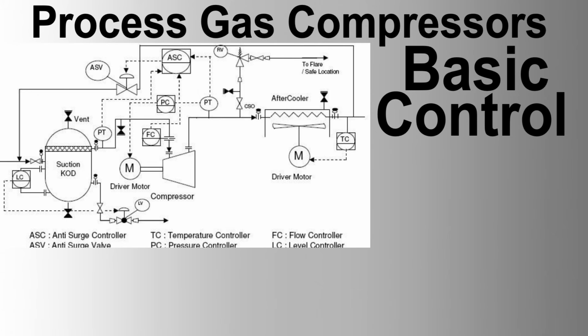Controller, anti-surge controller, processes flow and pressure signals to detect potential surge conditions. Recycle valve, RV, opens to recycle gas from the discharge side back to the suction side to prevent surge. Variable frequency drive, VFD, adjusts the compressor motor speed as part of surge control actions. Operation. 1. Flow and pressure measurement. The FT measures the flow rate and PTs measure the suction and discharge pressures.